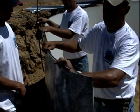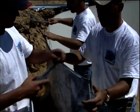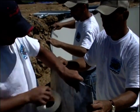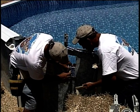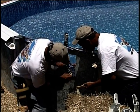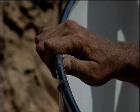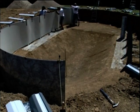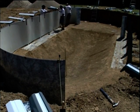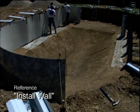As you work your way from section to section, secure the wall by placing stabilizer rails on the top edge of the pool wall. Use duct tape to secure the stabilizer rails. Alternate the larger and smaller diameter rails by telescoping the small diameter rail into the large diameter rail about 6 inches. Note that the stabilizer rails only telescope on the ends of the pool. Use the large diameter stabilizer rails between the side supports. Please reference Install Wall.